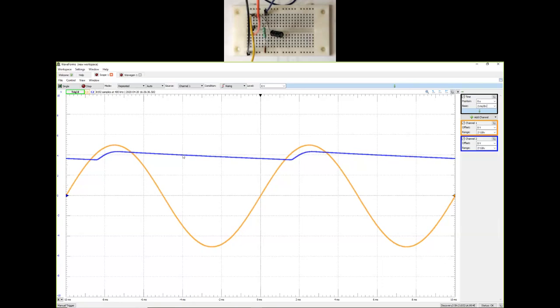And on the other side, I can reduce the frequency, meaning that I can spread these sinusoidal peaks apart further, and by doing that I will be allowing the capacitor C2 to discharge for a longer time, meaning the ripple voltage will be bigger in that case. So a poor DC rectified output, and we'll see both of these phenomena play out by changing the frequencies.